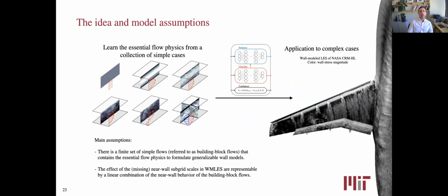And when I do that, what you see here in red is on average the mean flow direction, the mean velocity. There is a case where I have a free stream, where all the flow is uniform in one direction. The second case is laminar flow, so there is no turbulence, everything is smooth. And then the other cases have a turbulent flow, but the mean profile will change. In some cases, it will have some change in direction.